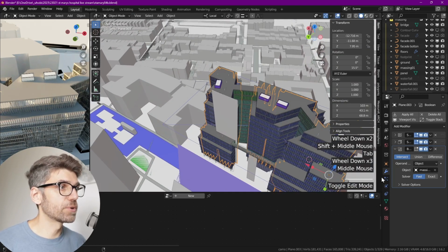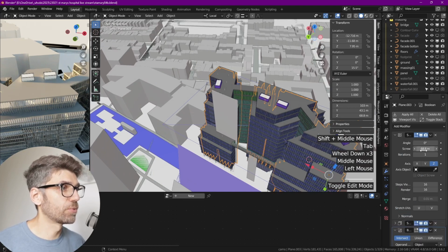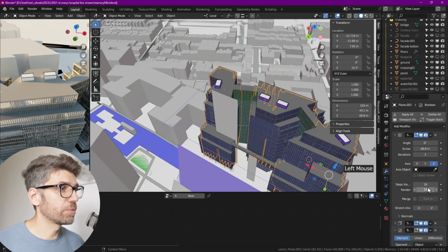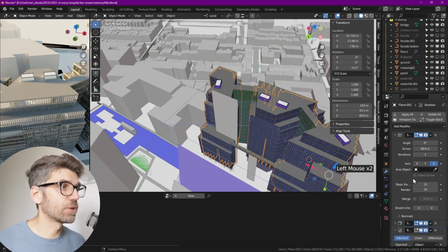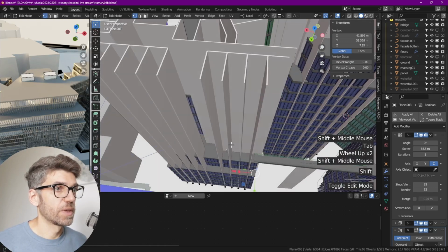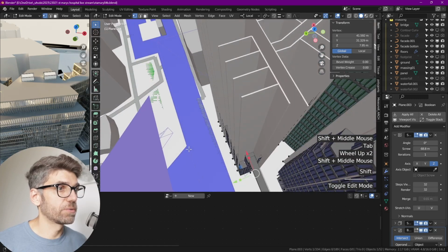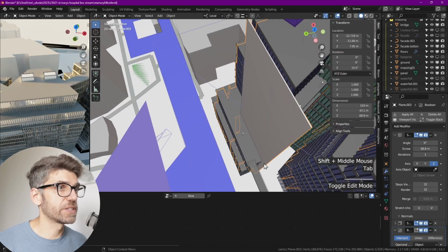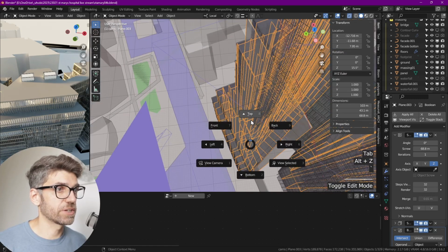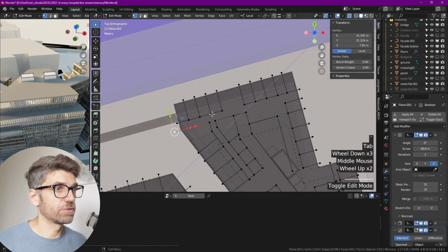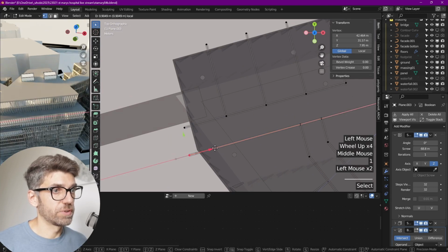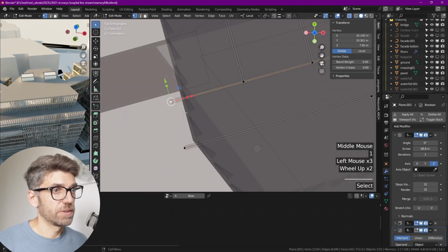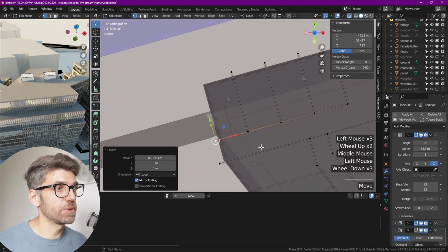And also having more subdivisions helps. So here in the screw modifier, the steps, we can try to change that to something like 32. Sometimes that helps, but not always, as you can see here. So what else can we do then? It's just hitting something on a funny angle where it's not really happy. Usually it's exactly at a point where it might have an intersection. So let's go and try to modify, I think, was it this wall? First off, if we move that further in, that's far enough from an edge, so it shouldn't be too much of a problem.